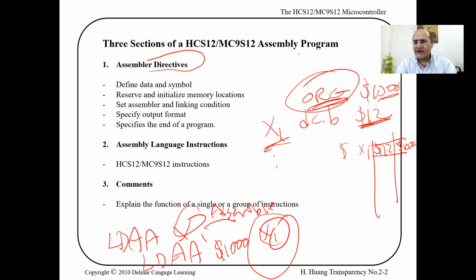The origin, go look for it in the instruction set. You will not find it in the instruction set table. It's not an instruction. There is no machine code for it. This is a directive for the assembler. No machine code will result from it that you would run on the processor. We call these directives.